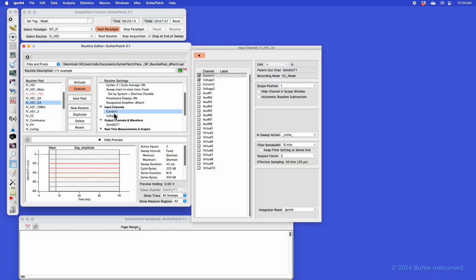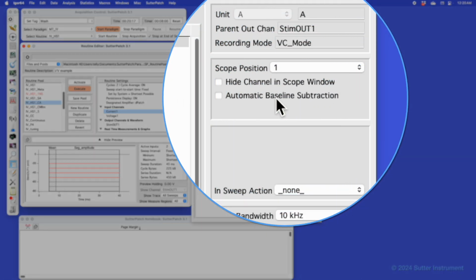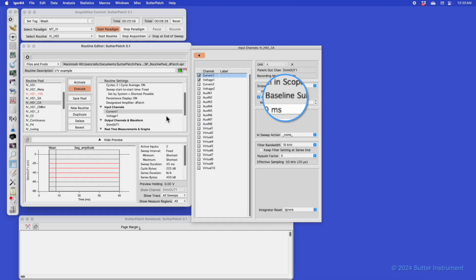Another change that we've made, again based on a virtual signal, is the baseline subtraction. We've made a more simplified version where you just specify the region from the starting point to a particular time. It takes a mean of this value and then subtracts it from the raw data trace. This information is stored with the data trace, so down the line during the analysis, if you'd like to see the data in its natural, unbaseline-subtracted form, you could easily do that from the data navigator. And I'll show you how to do that.